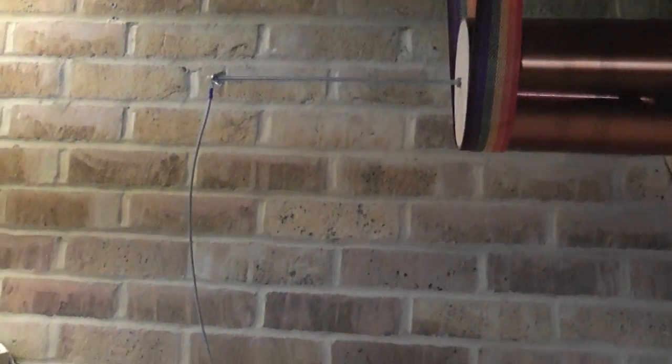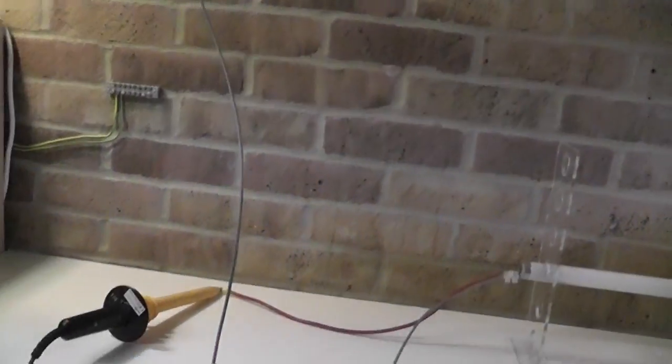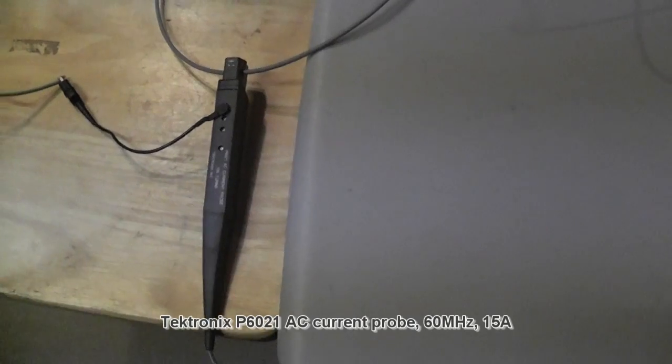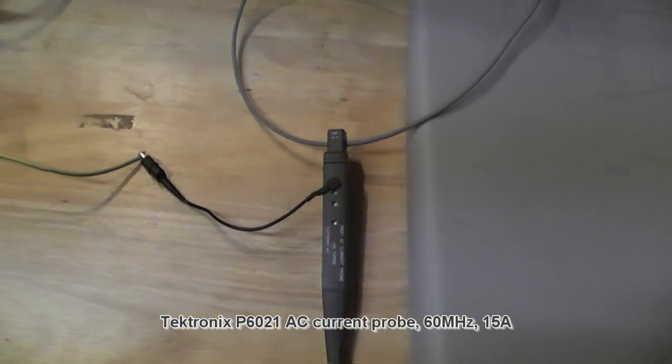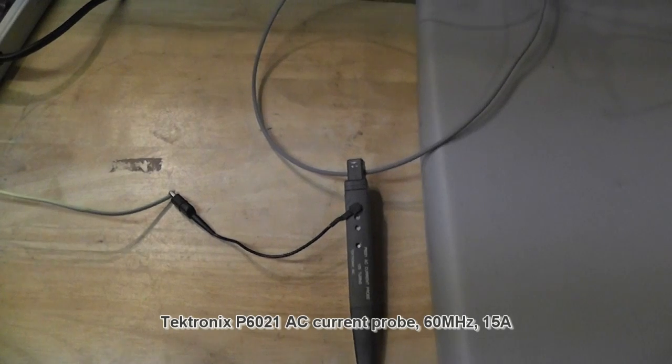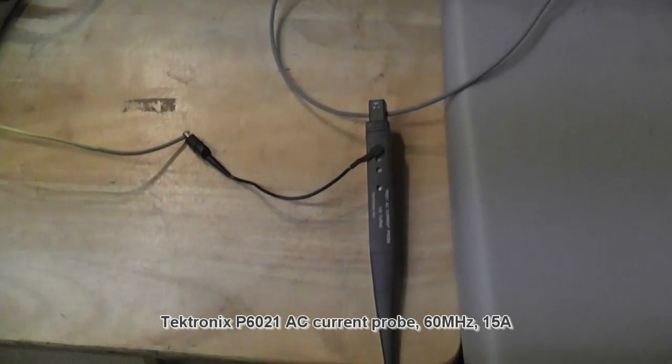On the so-called low side, we use the P6021, a current probe. Here in this example I have grounded it. Normally you would do a so-called floating measurement without grounding.